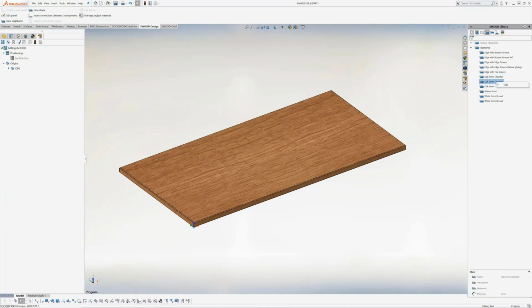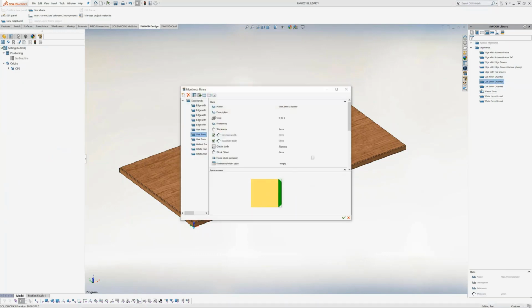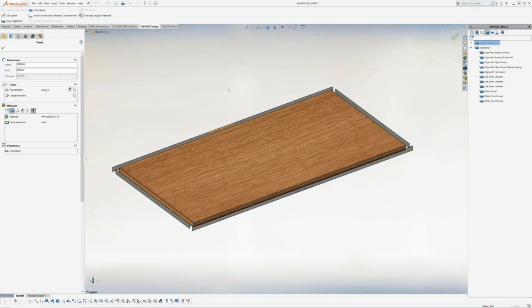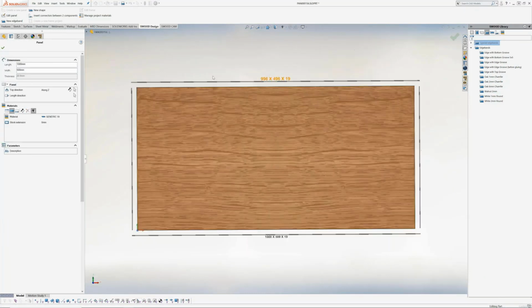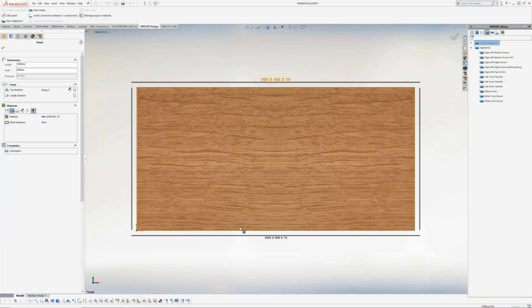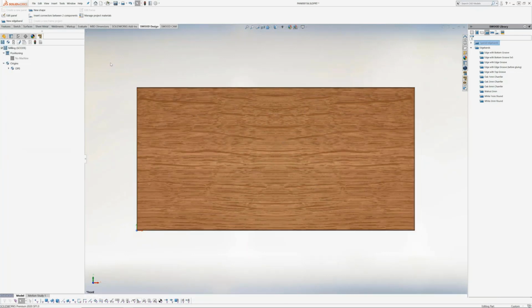And if we come back after that to our edge band definition, we have the stock offset parameter to be able to manage the cut list information regarding the process on the edge bander we will apply. So that's something we can directly see in the edit panel definition with the final panel and the cut list definition.